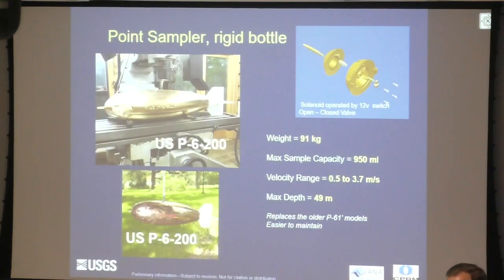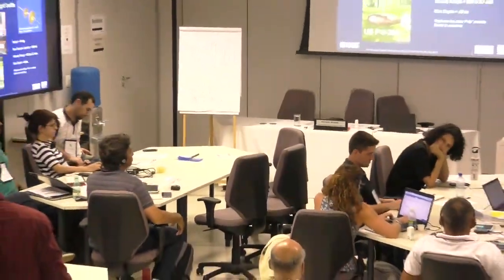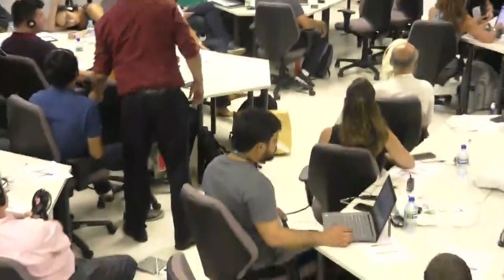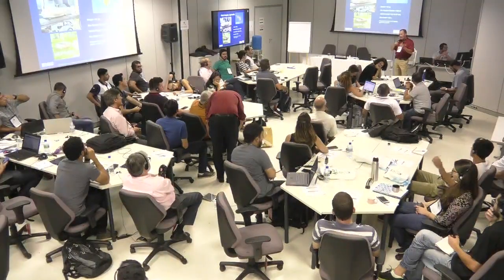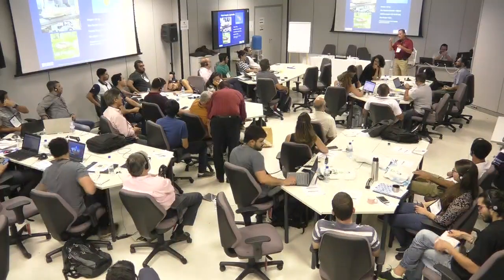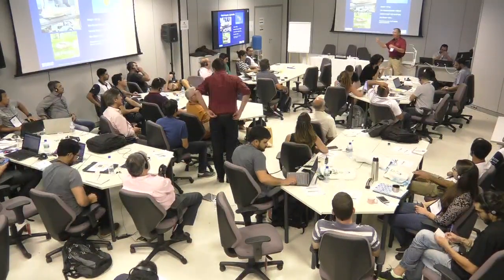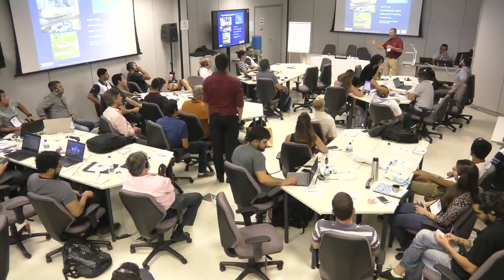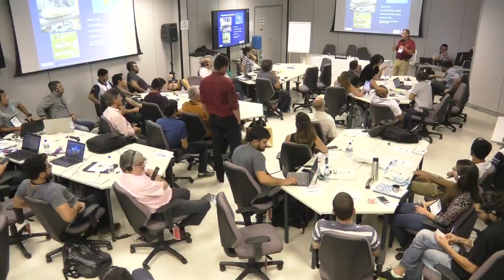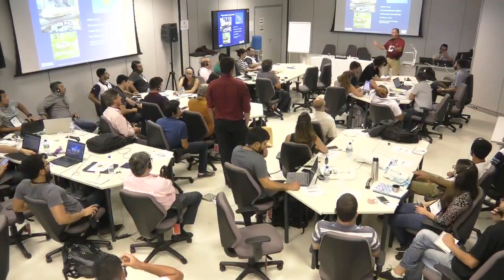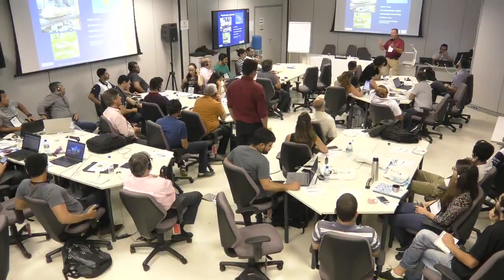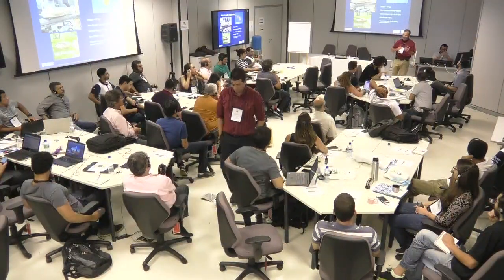The waypoints that I showed you that we mark as we're collectively accumulating discharge. Do you remember when I showed that slide where we'll make one pass with the ADCP and then we'll compute our sections, and as we're moving back across, we'll select a waypoint for that section. And we can set all of those points, and it gives us the option of coming back to the first section, or we can start on this side if there's barge traffic here. And so it gives us options, so we don't have to start over completely with where we are.